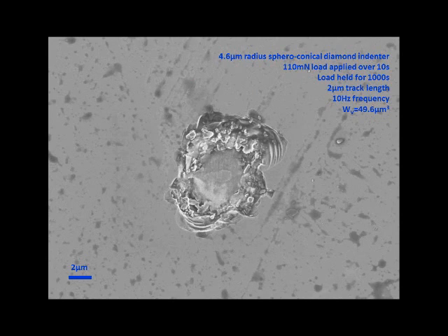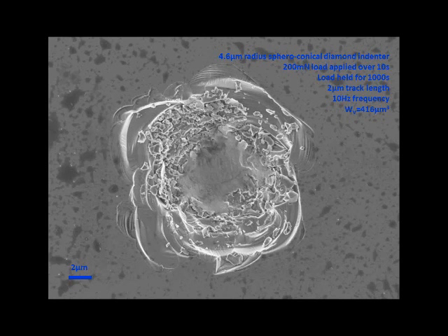Same test conditions here, apart from the applied load. In that case, load was increased to 110 millinewtons, resulting in clearly deeper wear scar and almost 50 microns wear volume.